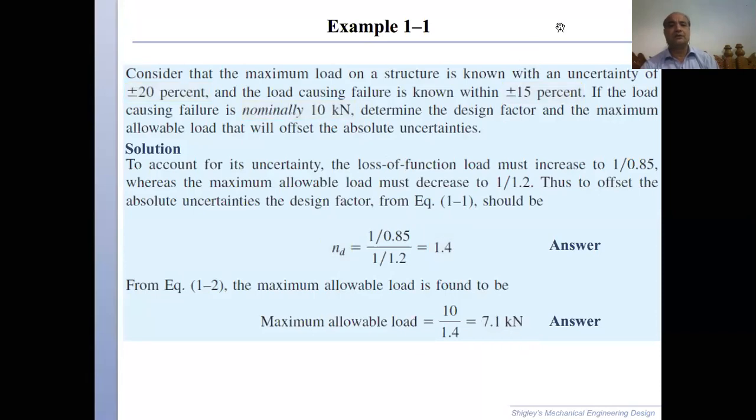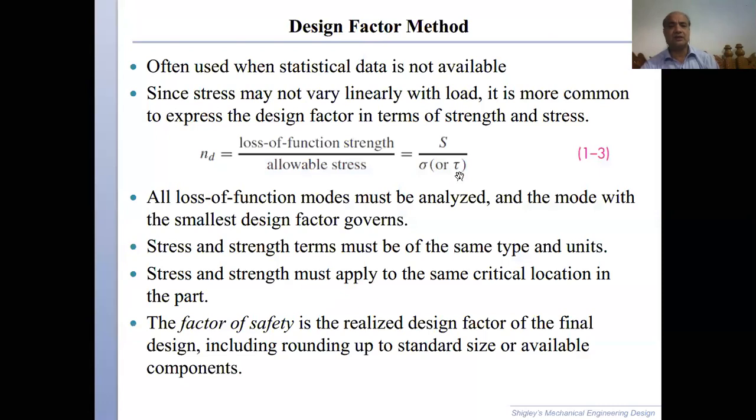In this design factor, there is also a factor of safety that you already knew about, and the formula for the factor of safety and the design factor is the same. Mathematically, they should be the same. The only difference between the factor of safety and the design factor is that we start with the design factor, and then when we are doing calculations, we might be rounding things.